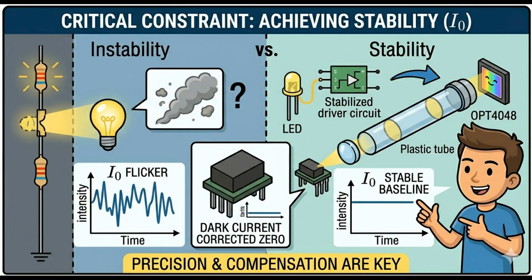When you start building a transmissometer, you'll find that there are some problems. Most of mine are shielded. The octo-rings are shielded. However, I'm working on a longbow that is not shielded, and you have to come up with some methods for compensating for the sunlight. I want to measure rain. I want to measure fog. I want to measure high humidity. And I've got some techniques, but you have to make the system stable otherwise, so you know that your medium is what you're measuring and not other things.